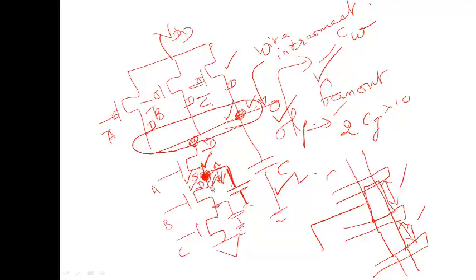So here the parasitic capacitance is due to the area and peripheral capacitances as defined in the model, and how wide a diffusion layer you are taking, how wide you are taking your poly layer, and what distance you create between these two. All these define how much internal nodal capacitance there is.